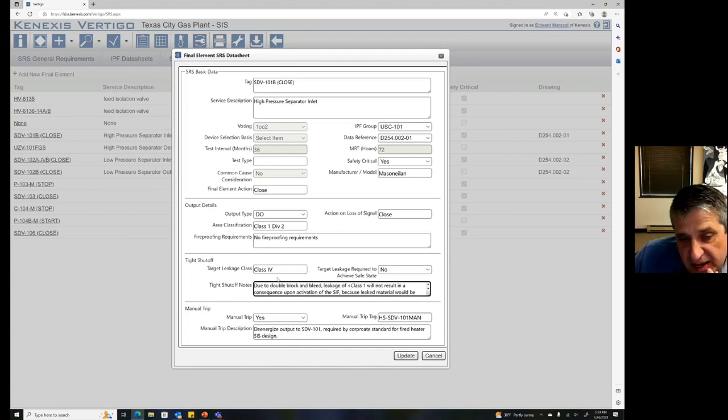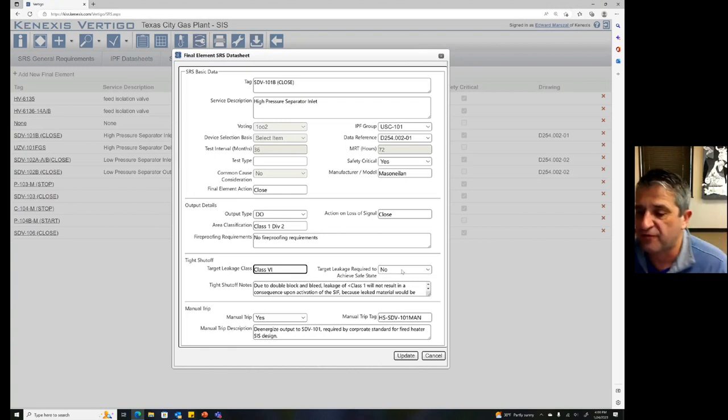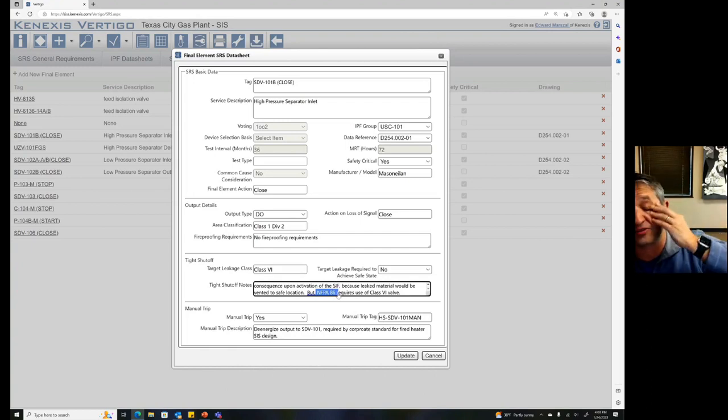I'm basically saying that the valve does need to be class 6, or actually I called it class 4. Let's do that again, class 6. But I'm saying that class 6 is not required for IEC 61511 compliance. There's another standard, and in this case, I'm just pulling a standard out of the air.